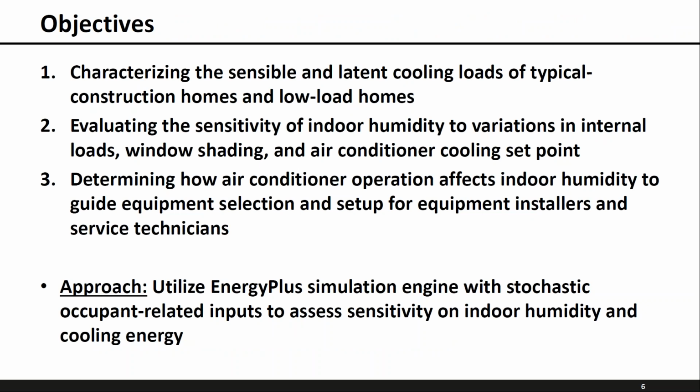So there are really 3 objectives to our study that we're going to focus on today. The first is looking at the sensible and latent cooling loads in a typical new construction home and also a low load home. And then we're evaluating the sensitivity of indoor humidity to variations due to occupants, such as internal loads, window shading, and air conditioner cooling set point.